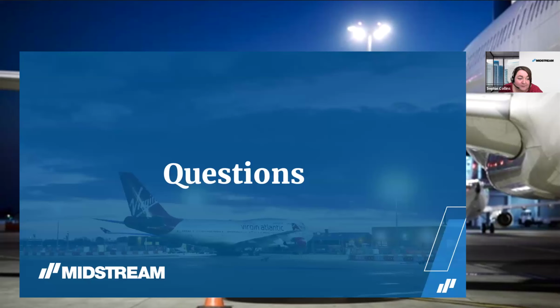Brilliant, thank you. And there's part 2. How do you interpret measuring vertical uniformity in the relevant direction? Well, we just discussed this. The uniformity is calculated in the same way as the horizontal, by taking into account the average lighting, minimum lighting, and measuring points. The relevant direction depends on the interpretation of the relevant normative in your country, whether it is single direction or 2 directions.